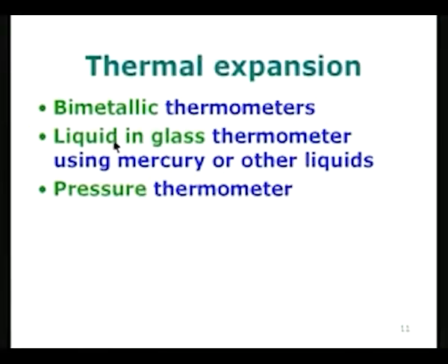It can also be used in many applications. It can be a thermal switch. When it bends, it will make or break a contact, and therefore it can be used as an electrical switch also. That means that at a preset temperature, it will open the switch, and yet again when it cools back, it will remake the contact, and so on and so forth.